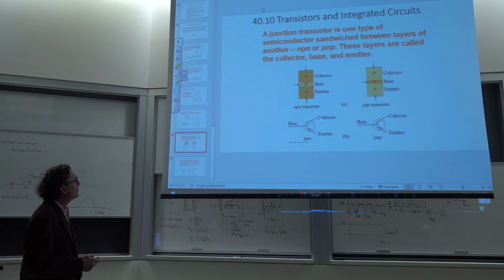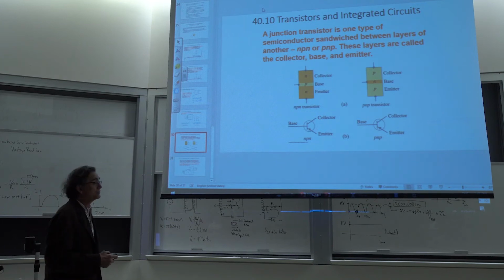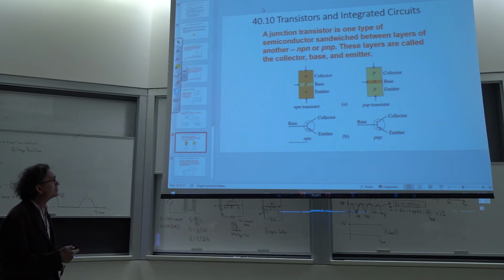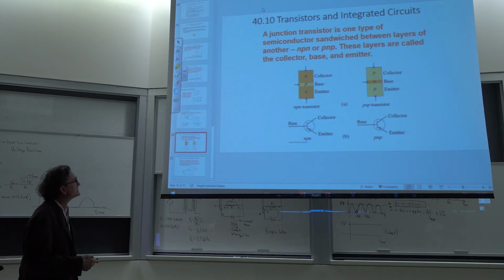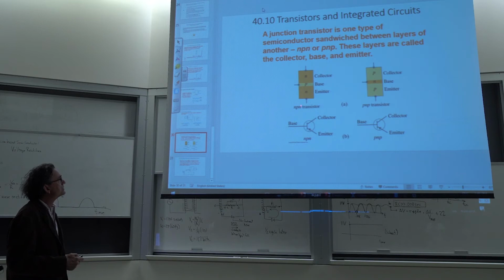The collector actually collects electrons, right? So in the normal operation that we're going to discover, when this device is active, we're going to get a large current, not only going through the P through the N, which is forward bias here, but also from NP to N, down all the way through here. So the general flow of current is going to be vertically down, either from the base to the emitter or from the collector to the emitter.